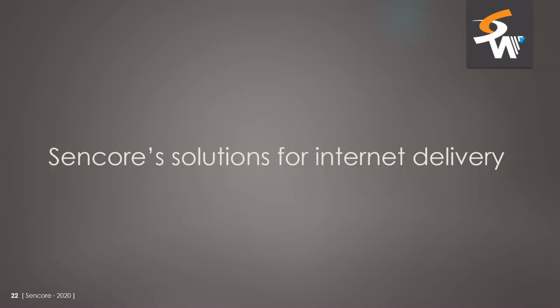All right, some more questions here. Can you expand on the details of the encoding capabilities? Does it support 422, 8-bit, 10-bit? What's the video quality like and the latency? Sure. The encoding that's in this product is primarily geared towards distribution. So 420, 8-bit for the most part, H.264.